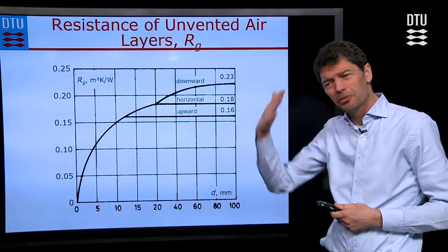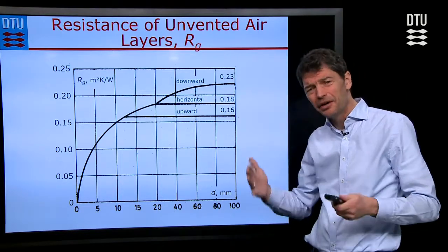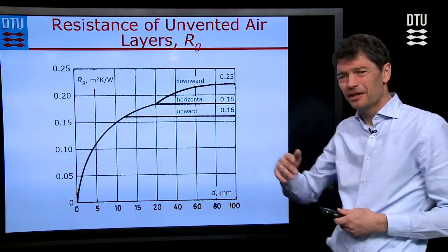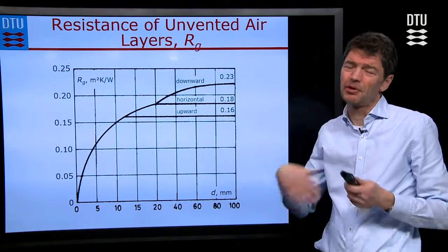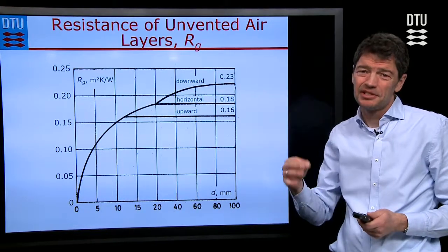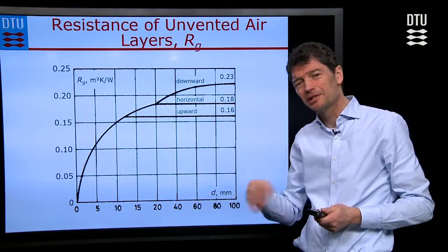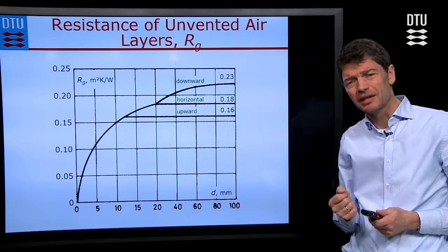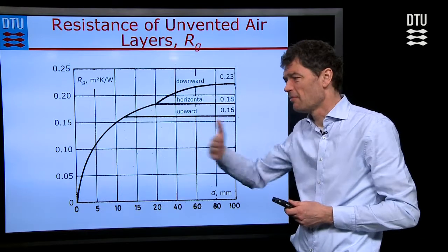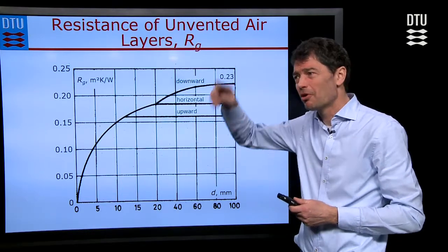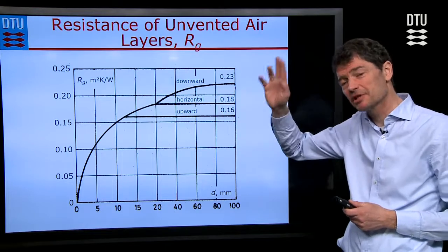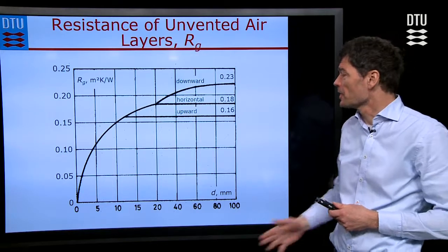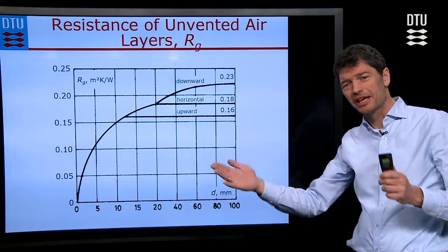Let's consider one of the small extra topics in this subject. There could be a layer inside of a wall, which could be an air layer. In an air layer, we have both convection and radiation, but very often in standard calculations we can simplify that by using standard thermal resistances. That depends on whether we have a horizontal or vertical heat flow, and if it's vertical, whether it goes up or down. And then it depends on the thickness of the cavity.